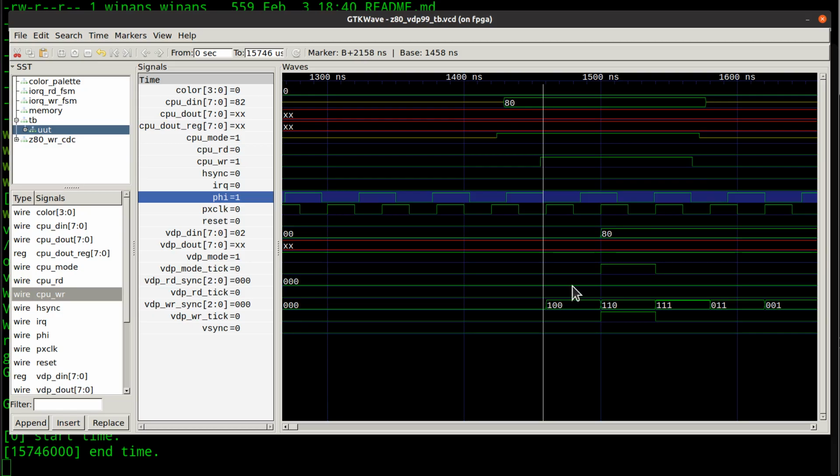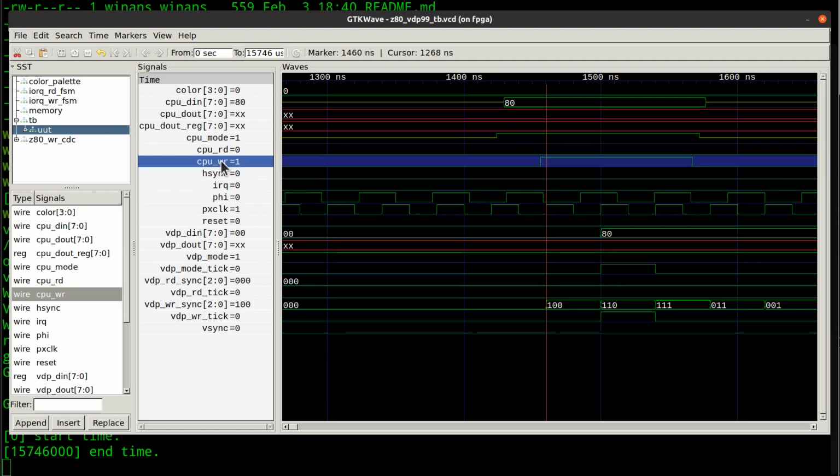So what we do is we're going to create a shift register. And we're going to say every time there's a rising edge here on phi, I'm going to take what I believe is the latest, greatest. I'm going to just clock in and latch whatever's on this right register up here, and it may or may not be metastable. Odds are, even if it does wander around a little bit and it's metastable, it'll settle down by the time you get over here.